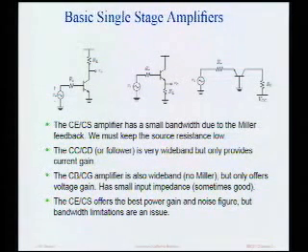How about the common base amplifier shown here? Again, common base amplifier, it's wideband. It doesn't have the same issue with the Miller effect, but it doesn't have any current gain. It only has voltage gain, so it's not going to give us as much power gain as a single stage amplifier. Now, I'm not saying that they're bad amplifiers. They're very useful. They're particularly useful when we use them in conjunction with other amplifiers. In other words, when we have 2 stages or 3 stages, or if we use feedback.